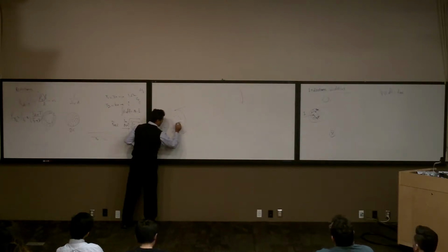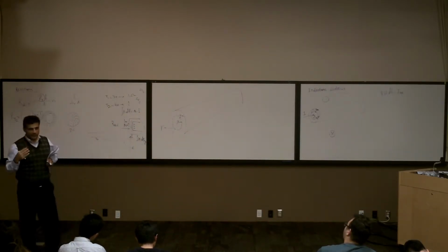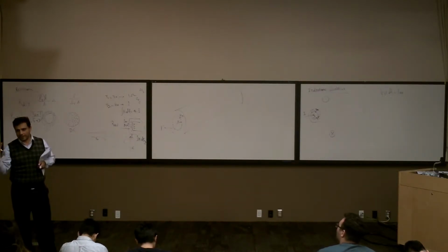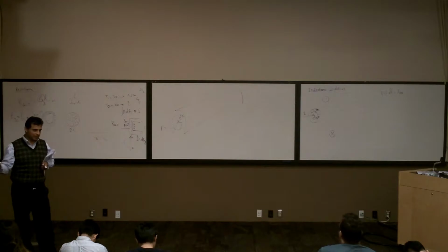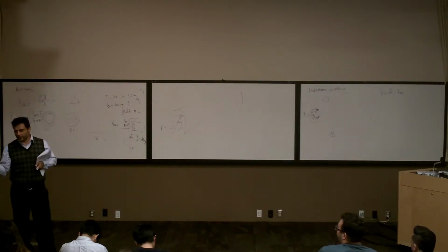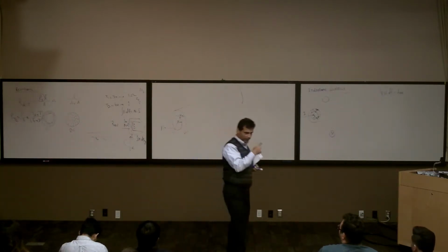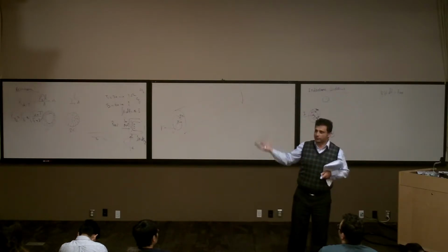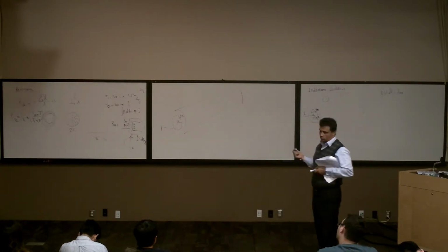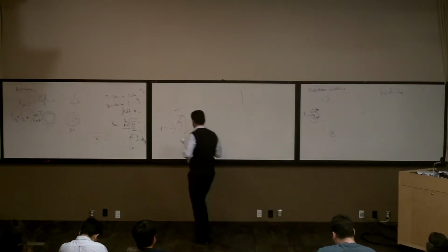This circle is x, and I want to calculate Hx here. I call it Hx because it's at the radius x. Why am I calculating Hx? Because if I calculate Hx, I can calculate B, right? B is equal to mu H. If I calculate B, I can calculate phi. Phi is B times A. If I calculate phi, I can calculate lambda. Lambda is the number of turns times phi in general, although here there are no turns and we need to talk about that. So basically, I'm going to start from H, then go further and calculate lambda and finally calculate the inductance.